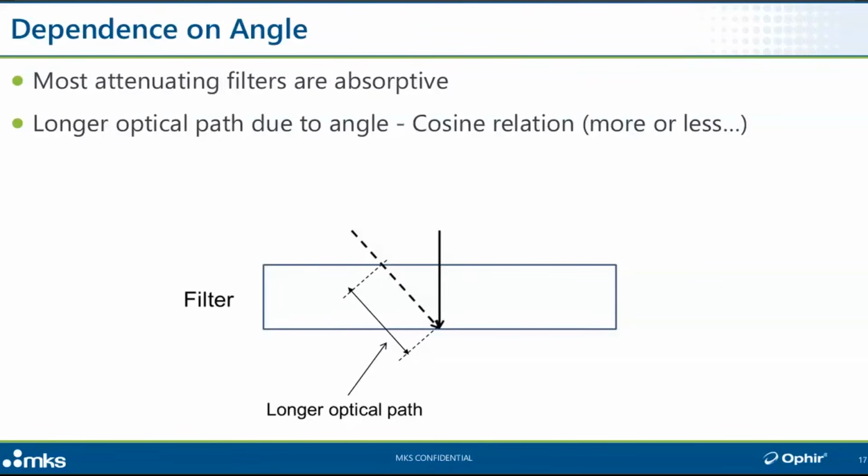So first of all, as a general rule, the transmission, reflection, absorption behavior of materials in general is affected by angle, if you remember your basic physical optics. As we approach grazing incidence angle, materials tend to become more reflective. Photodiodes are no exception. So the absorption of light by the detector is to a small degree angle dependent, but much more significant than that.